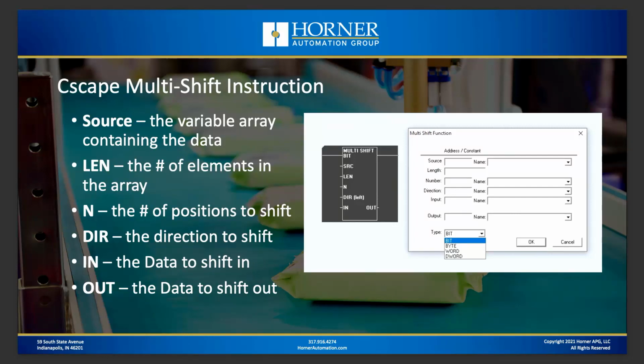However, if you're talking about variable-based ladder, there is where you're really talking about variable arrays. So you create a variable, whether it's bit type, integer type, real type, whatever the proper type may be for your application, and then you assign it a dimension equal to the number of bits or words or floating point values that you want to manipulate in your shift register.